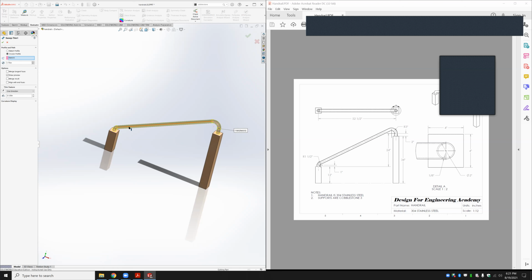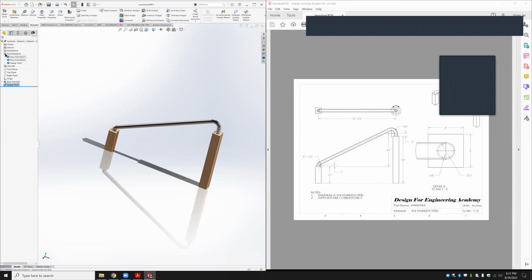Merge them, exactly, because that way you can assign different materials to each one, like the rail. So when you look up here, once I did that, I then have 3 bodies up here, and I'm able to select the material type for the bodies independent of each other.